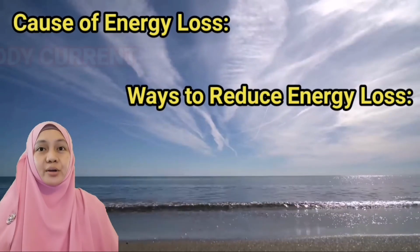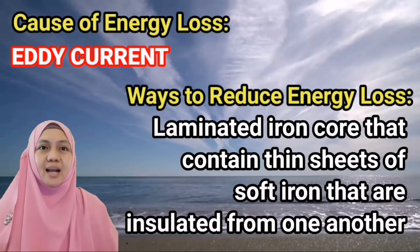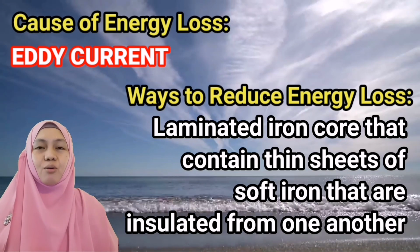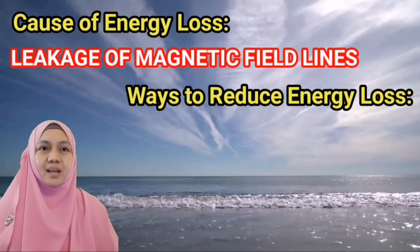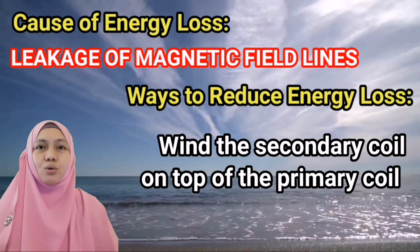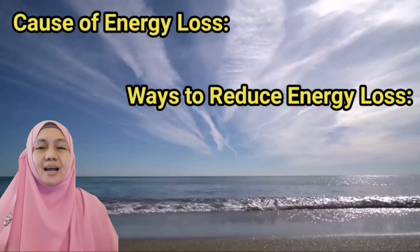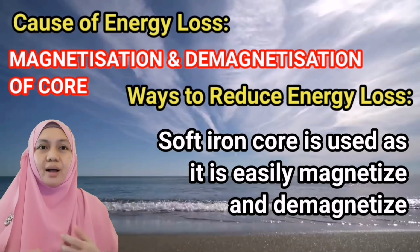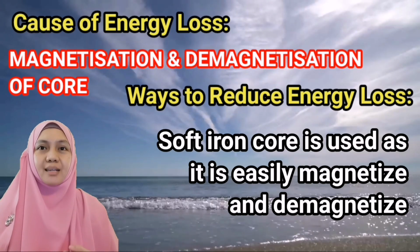Number 1, eddy current. To reduce eddy current, we are using a laminated iron core that contains thin sheets of soft iron that are insulated from one another. Second, leakage of magnetic field lines. This can be overcome by winding the secondary coil on top of the primary coil. Number 3, magnetization and demagnetization of the core. So soft iron core is used as they are easily magnetized and demagnetized.